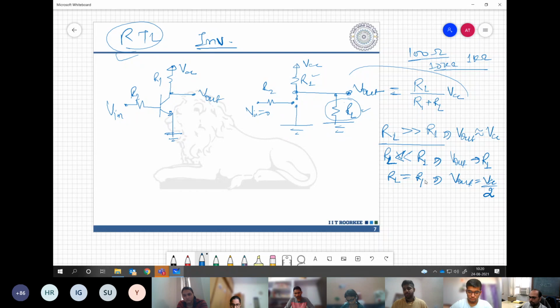Isn't it? Say your R1 is equal to 4 times RL. Now your Vout would be what? VCC by 5. Isn't it? Yes or no?